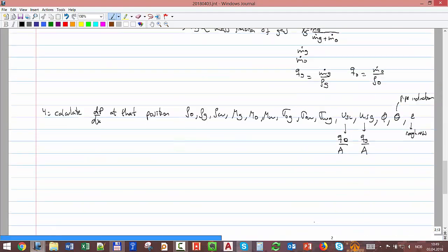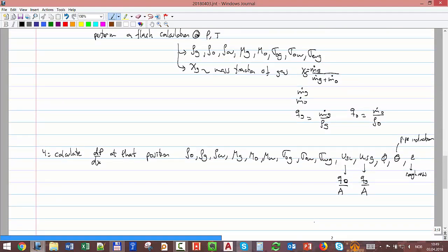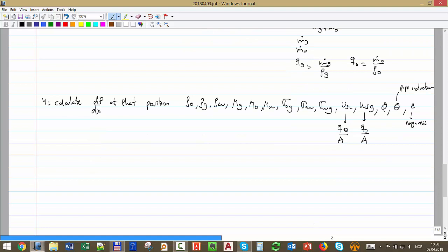Okay, these two guys that I have here, the superficial velocities, but it also depends on all the other properties, densities, viscosities. The inclination of the pipe is not the same if the pipe is horizontal or if it's vertical. So it depends on all of that input, and I'm not going to go too much in detail there. But basically, there are different approaches, but you can use correlations. Okay, people try to make, based on all of that input, a correlation for delta P.